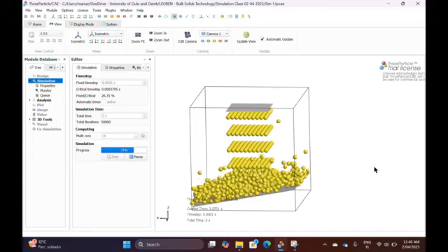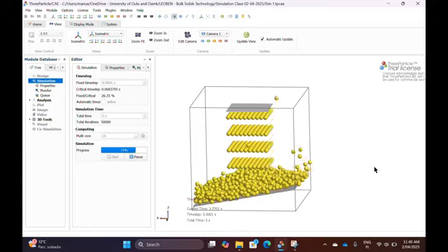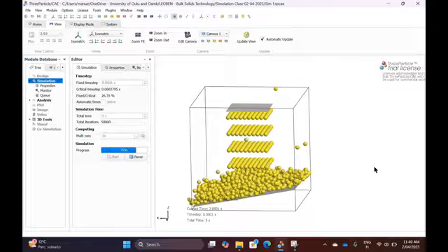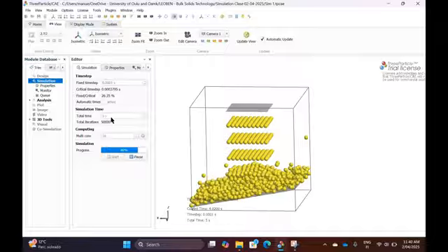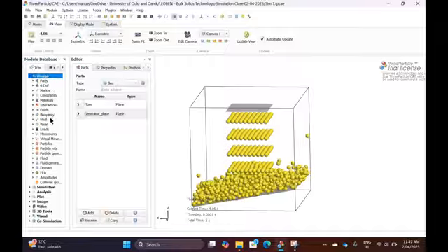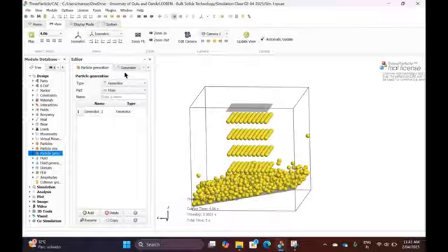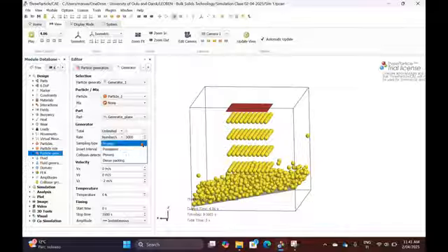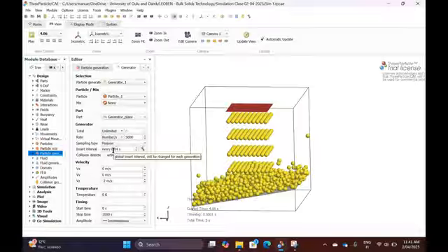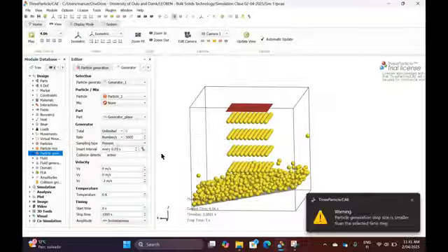Good. Now another thing that I did not want. I said I do not want this perfectly regular patterns to occur. Probably go to design, particle generation, that's where we left before. And here is regular. Let's change that to Poisson, which means randomly distributed, and I want a little bit denser generation, so more particles after another, so not every 0.2 seconds, probably every 0.05 seconds, or whatever.